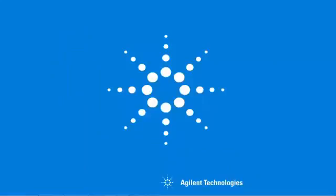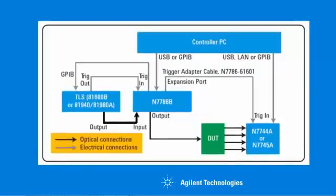The required connections for the IL-PDL measurement are shown below. Both the polarization synthesizer, the N7786B, and the multi-port power meter are connected directly to the control PC. There's a GPIB connection between the N7786B and the tunable laser. Additionally, we have a trigger connection. There's a BNC trigger output on the rear of the tunable laser, which is connected to a BNC trigger input on the N7786B. And there's also a trigger connection between the N7786B and the multi-port power meter. This is a special cable that ships as part of the N7786B. All the other connections are optical.